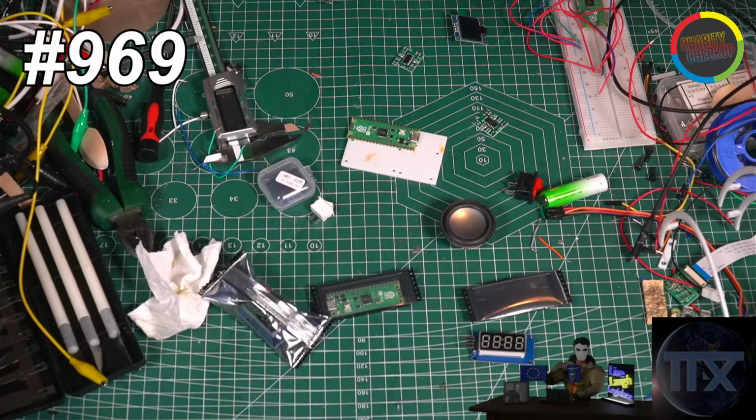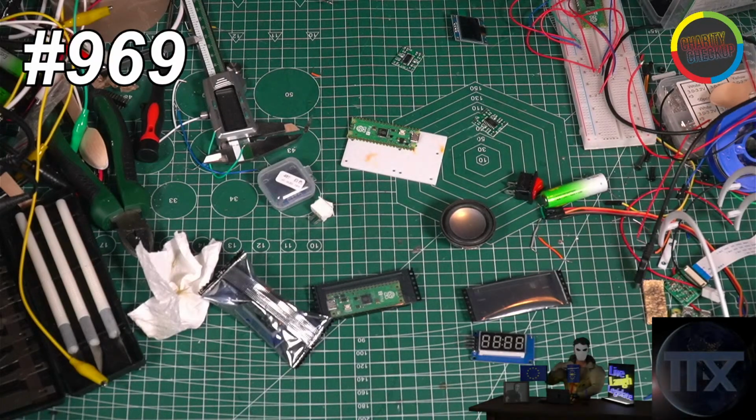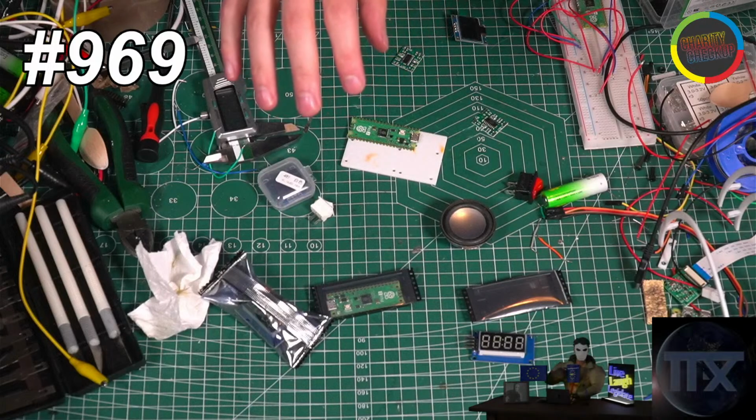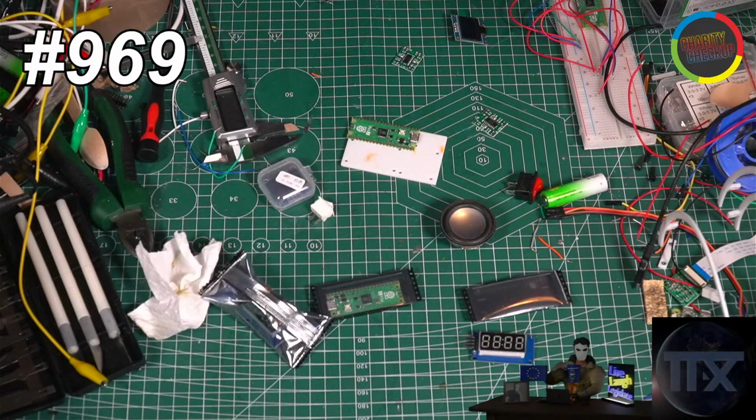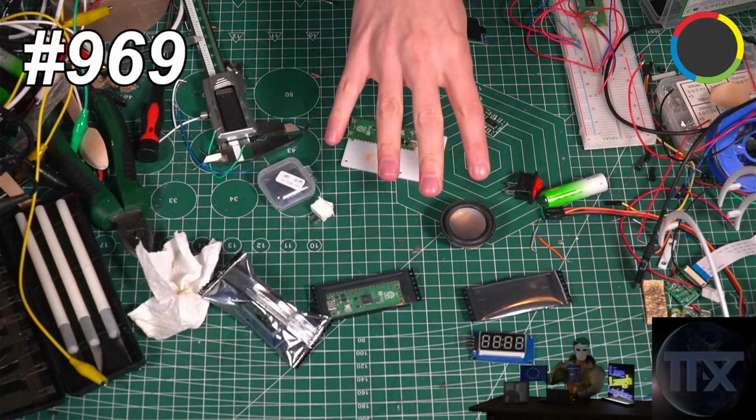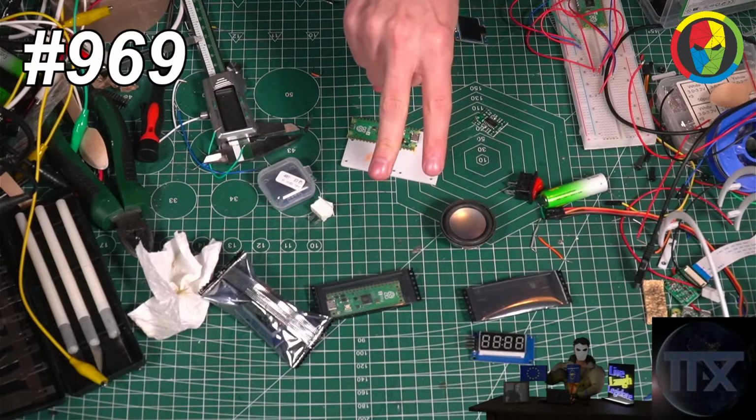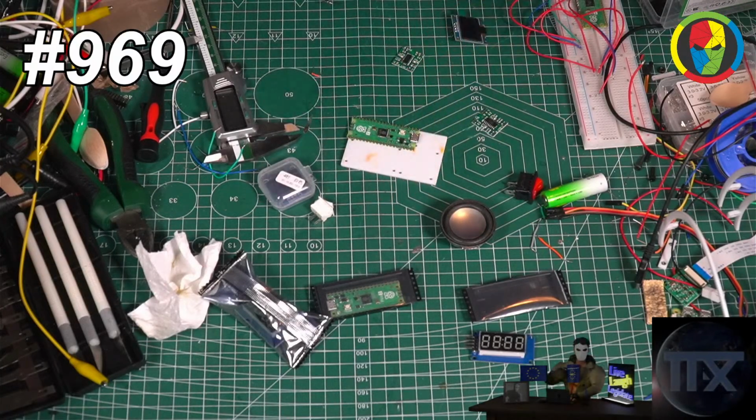Genuinely, in order to get the OLED display to work, all I had to do was plug in 4 cables, ground, voltage, data, clock, then get a library from GitHub. Yeah, because you don't even need to write your own drivers. That's honestly not advised. So just get a MicroPython library from GitHub, and then just run it, and it works already. It's all so much easier than people would believe.